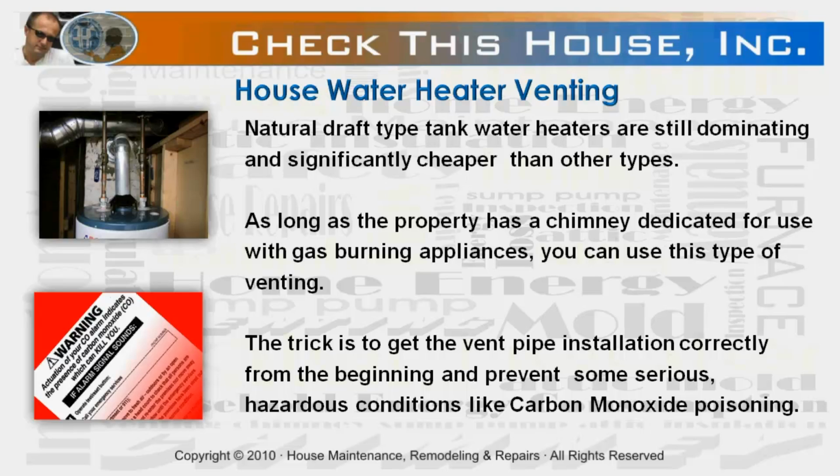Natural draft type tank water heaters are still dominating and significantly cheaper than other types. As long as the property has favorable structural conditions and a chimney dedicated for use with gas burning appliances, you can use this type of venting. The trick is to get the vent pipe installation correctly from the beginning and prevent serious, sometimes very hazardous conditions like carbon monoxide poisoning from ever happening.